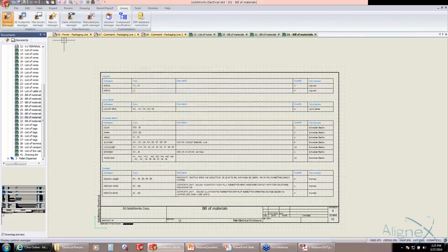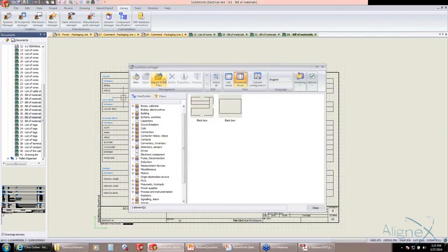If we step into our Symbols Manager, we have the Import DWG Files icon available to us right there. If it happens to be a symbol coming from AutoCAD Electrical, we have the ability to cross-reference their attributes to ours and also maintain those and bring the symbol in directly with very little work needed to convert it.